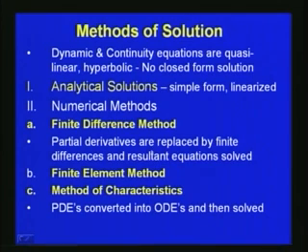We can use variational principles, like different finite element methods. This is an integral form where we approximate the governing equation with respect to an interpolation function, then integrate with respect to the system, find the weighted residual, and then approximate. So, that is the basic principle behind the finite element method.